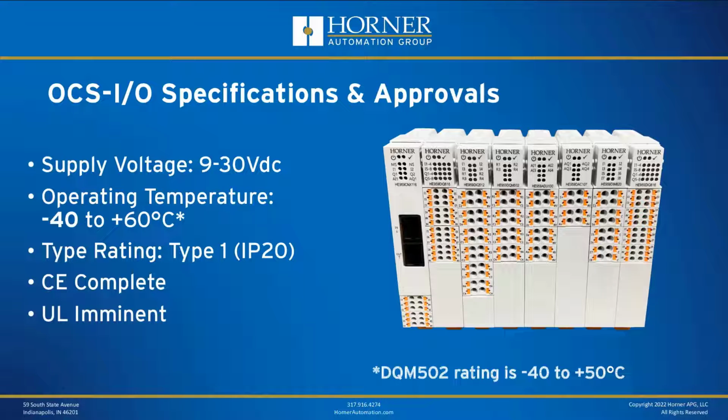So if we take a look at some of the other specifications, you can use either 10 or 24 volt levels with the OCS-IO. The voltage range, as you can see on the screen there, is 9 to 30 volts. I mentioned previously, it's got a wide temperature range of -40 to +60 with a standard product. That was by request of some OEMs that were interested in a wider, at least lower, temperature range than what we had offered on our other IO families. So we were able to accomplish that.